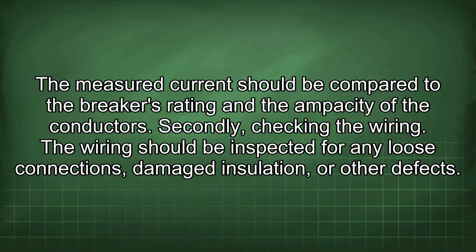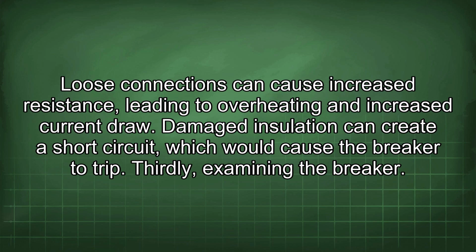Secondly, checking the wiring. The wiring should be inspected for any loose connections, damaged insulation, or other defects. Loose connections can cause increased resistance, leading to overheating and increased current draw. Damaged insulation can create a short circuit, which would cause the breaker to trip.